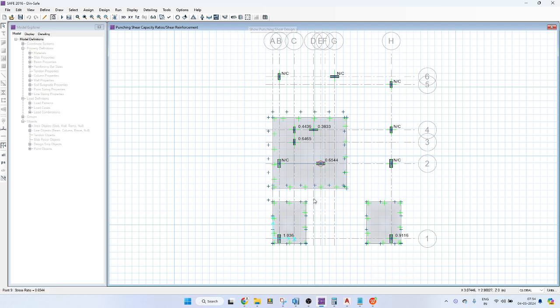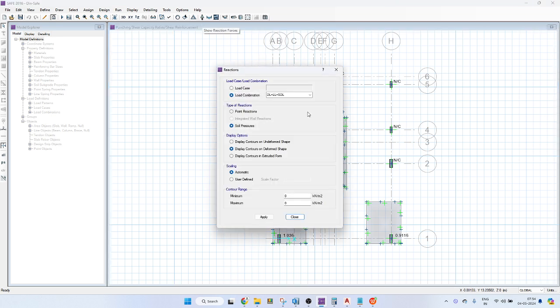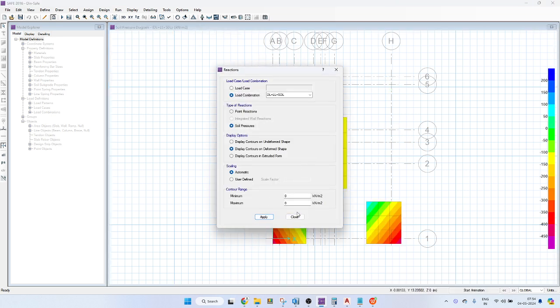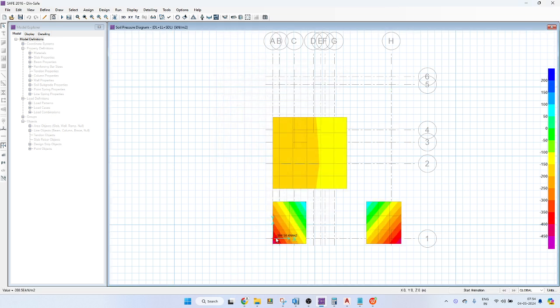This is okay. 30 inches is okay. 33 is too high. 30 itself they will comment. Okay, next. There, the sizes actually we can increase. See here and all, it is failing very badly, so we can only provide pedestals. But if we are increasing this also, it wouldn't be satisfying because this is an eccentric column footing, right? So it requires pedestal.